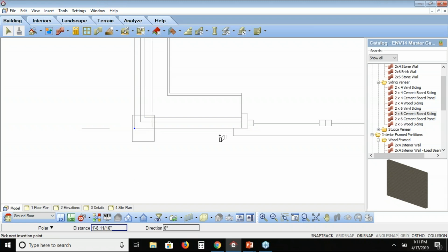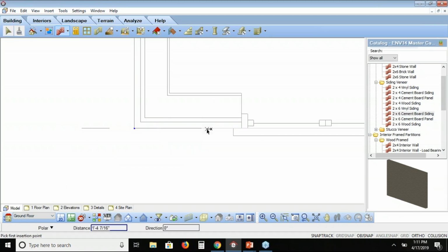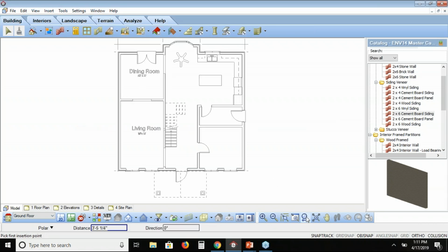I left click. And you can see a wall comes through there. I can also, when I'm drawing this estimate, use that as a baseline. So I'm just going to do one single line and track around that outside edge. And I zoom out. Now all I have to do is move my cursor to each corner, and as I come to each corner, I'm just going to left click. See how my cursor's got that circle with an X in it? It's snapping to those corners. It's seeing those edges on that vector PDF. So I'm just coming around, picking on those corners.